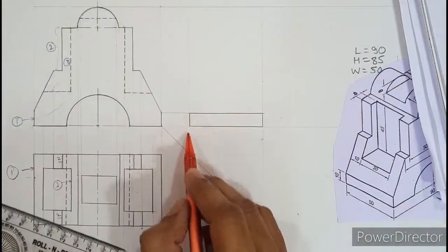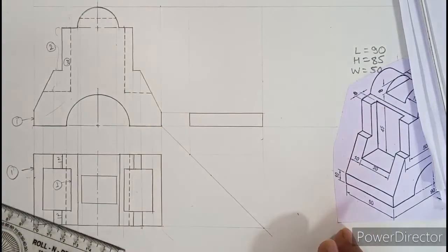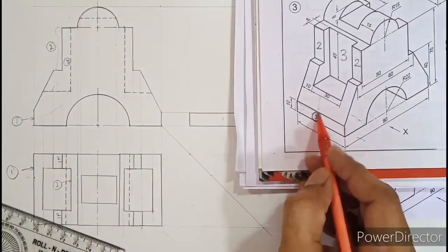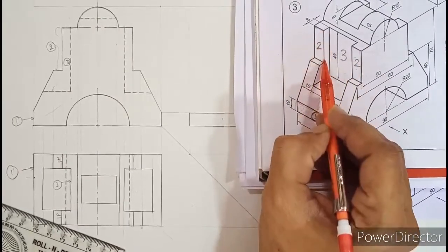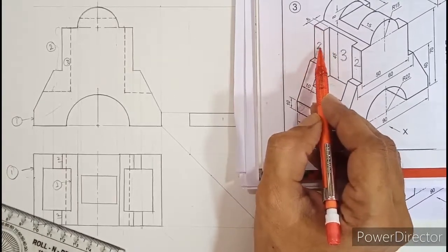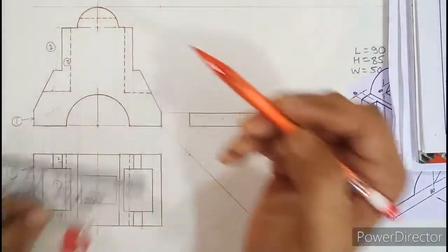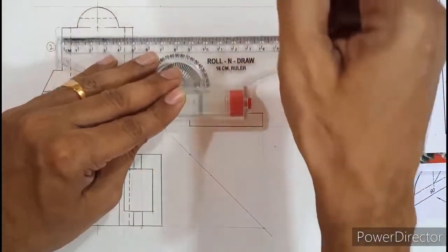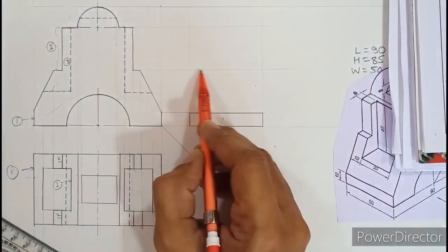So see, this rectangle of length 50 and height 10 is ready. So this was the first rectangle. So if you view from the side, this is that first rectangle what you can see. Now this second rectangle, height you will come to know from front view, and width from the top view, that is 10 mm. So this second height is already identified here. It is here. This is the second height. So let us project this second height on this side. Yeah, so it's done. Now the width of this second is 10.